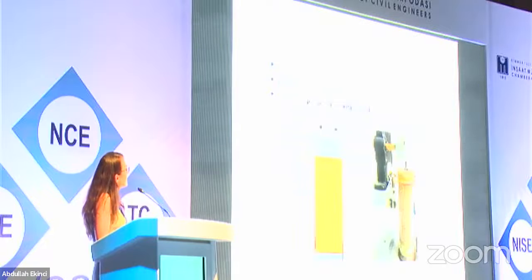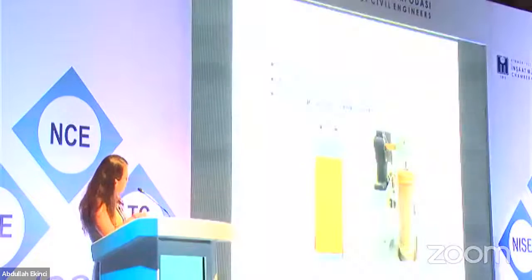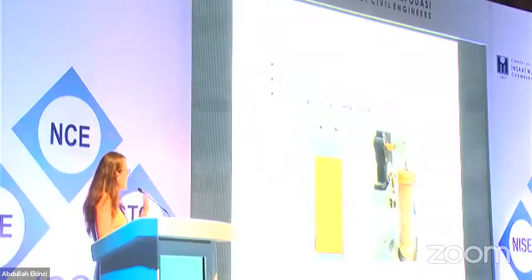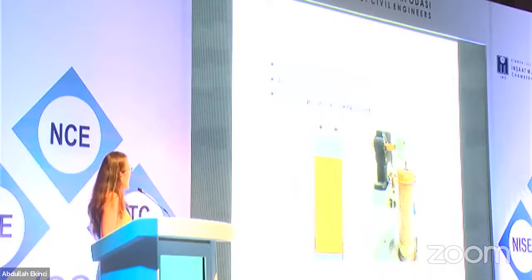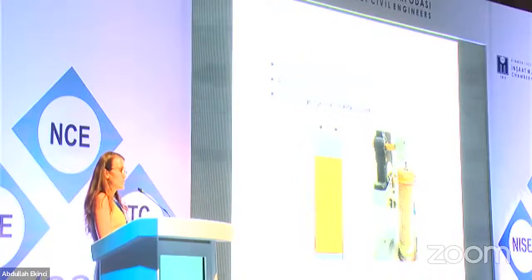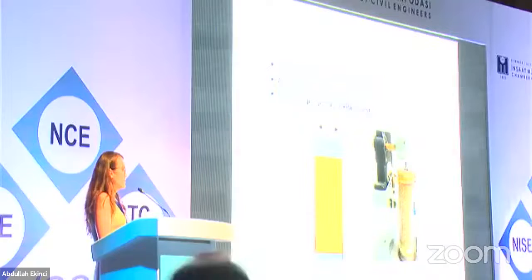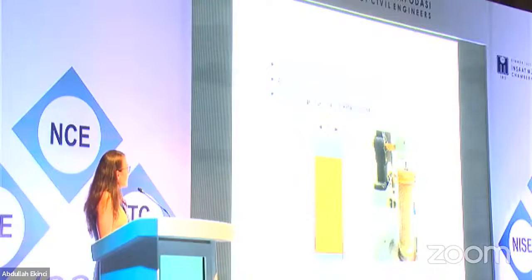The idea behind the cyclic shear test I'm going to talk about today is very simple. We are considering a cylindrical specimen, but without a water-filled cell. As you can see here on the right-hand side, the schematic representation, and the left-hand side shows the actually installed specimen in the experimental setup. Now, this specimen is loaded in horizontal direction cyclically with a defined frequency and loading amplitude. And you can see here the analogy to a simple shear test.